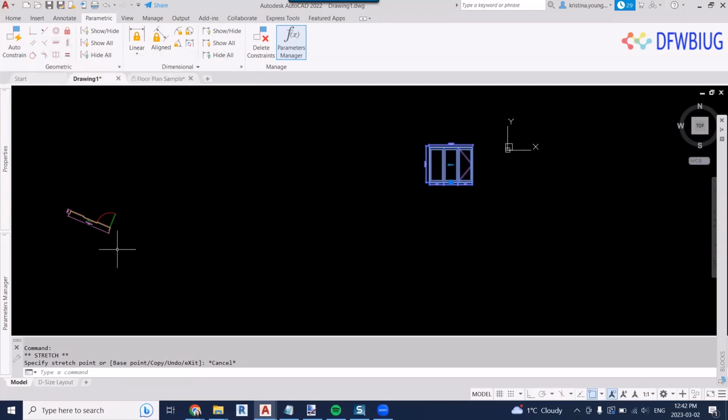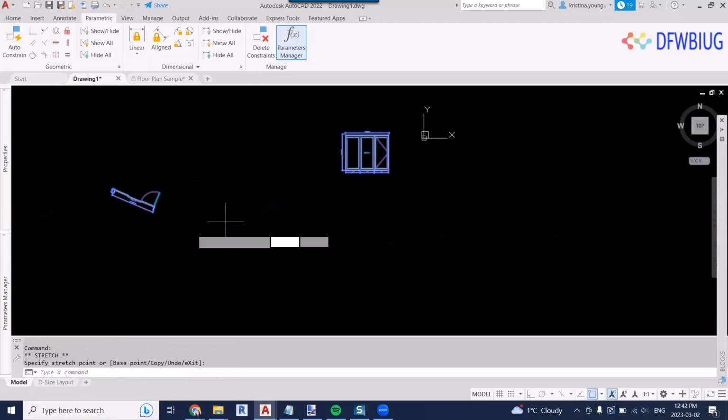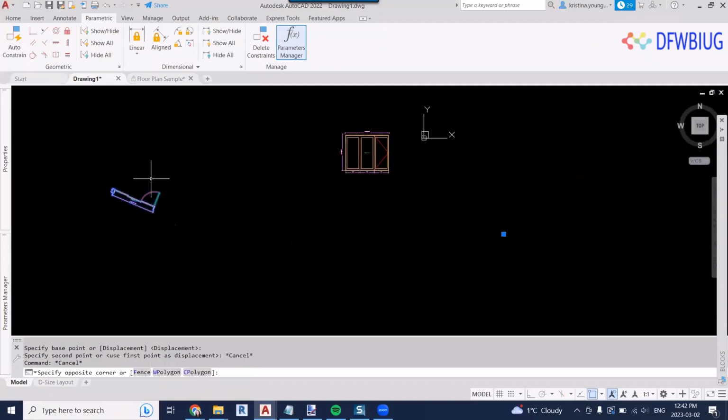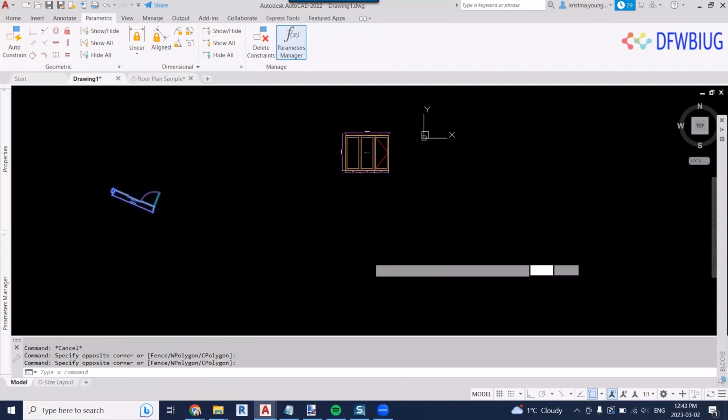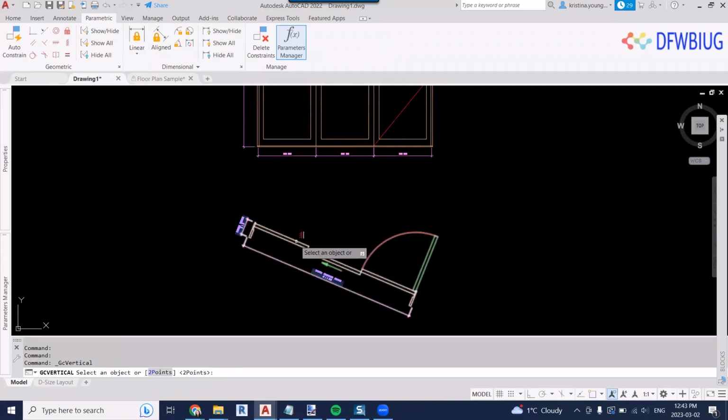So I have my door plan view here, and you can see that she might be a little wonky. And I want to fix that because I want it to align with this elevation. So first off, you can just rotate it. That's not a problem, but I like to add a little level of control to my files and making sure that things are just going to stay the way that I want them. Because sometimes you can see how I went to click on this plan view and I had my elevation still selected. Kind of can drive you insane a little bit.